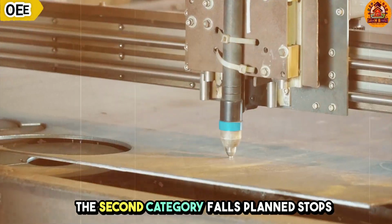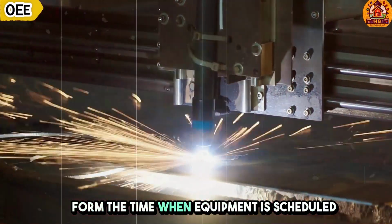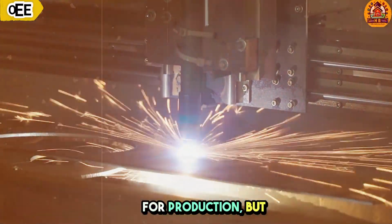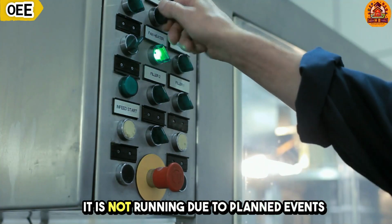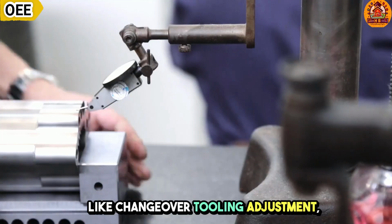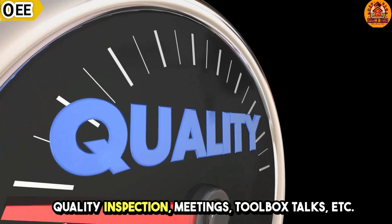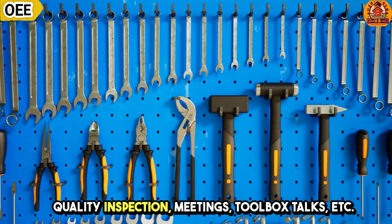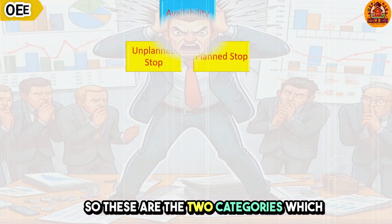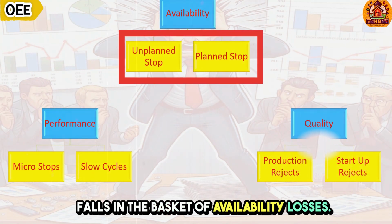The second category is planned stops. This is the time when equipment is scheduled for production but is not running due to planned events like changeover, tooling adjustment, cleaning, plant maintenance and quality inspection, meetings, toolbox talks, etc. So these are the 2 categories which fall in the basket of availability losses.